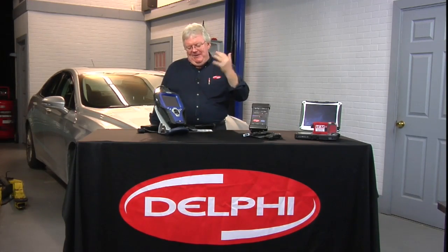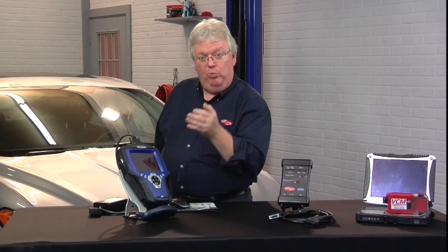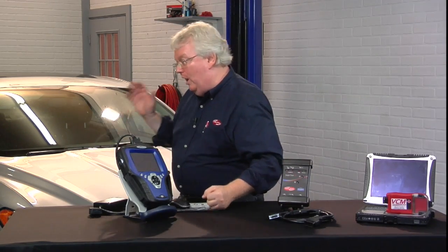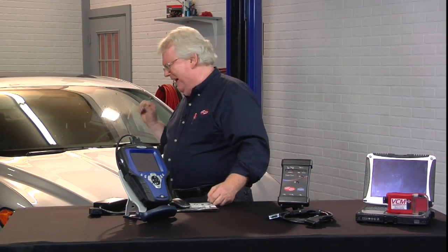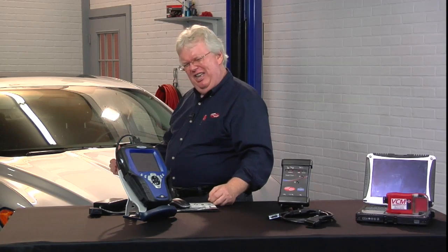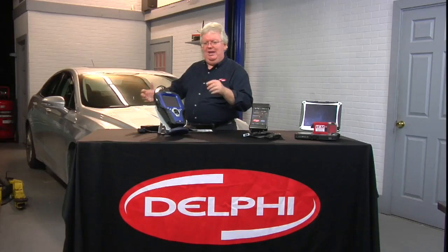It's a typical legal document. But FMVSS may or may not apply to this, but I've seen this as an observation: more 5-volt power supplies. Instead of one, and you short, let's say, one 5-volt sensor, we'll say an AC pressure transducer on the high side of the AC line. That shorts out, maybe the wire pinches or the sensor shorts internally, and now the whole 5-volt system is down. You don't have TPS working, MAP, baro, nothing.